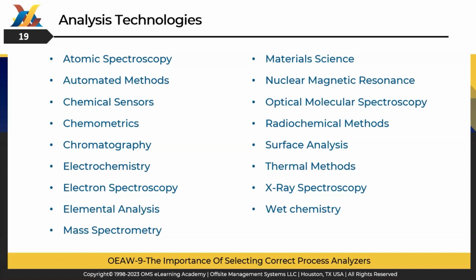Since the process analyzer results must be correlated to the standard laboratory analysis method, it's essential to select the analytical method from many available techniques. Here on this slide, we can see some of such methods, for example, chromatography, surface analysis. We also have to distinguish between ASTM-based analyzers and correlative analysis techniques. It's also important to realize that not all the laboratory methods are available for the process. If possible, it's recommended to consider various spectroscopy technologies, which are more reliable and easier to maintain than the other